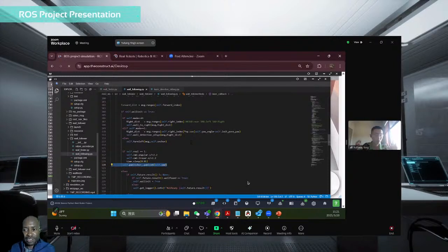So every time you send a command, the robot will receive it. It is good when we do simulation. But for the real robot, if you are sending too frequently, like more than 1,000 hertz, some commands will be missed, and sometimes we just send it once, and if it disappears, the whole program will collapse.